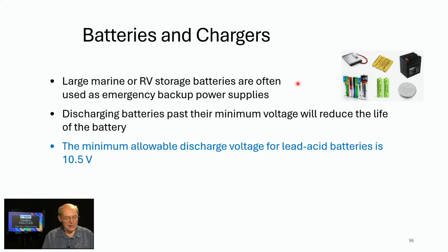So we're talking about large marine. These are usually lead acid batteries, can be used as backup. And if you discharge them too far, it'll damage the battery, it'll reduce the battery life. And this answer is controversial. What you want to answer when you get to this in the pool question, the minimum allowable discharge voltage for lead acid batteries is 10.5 volts.